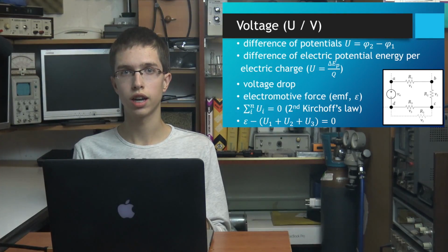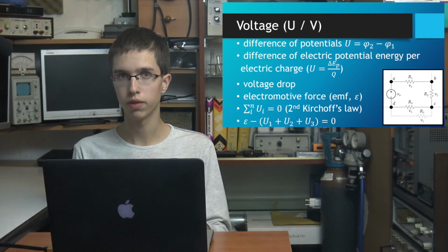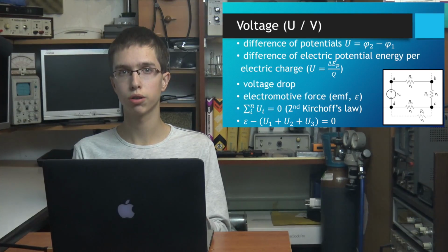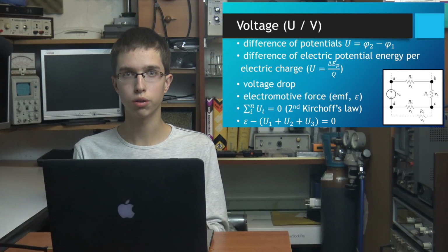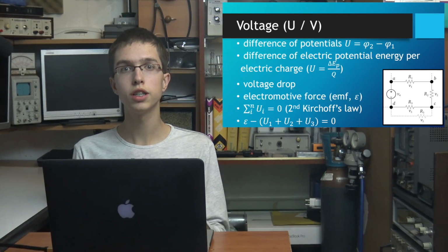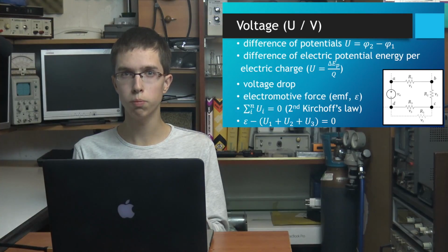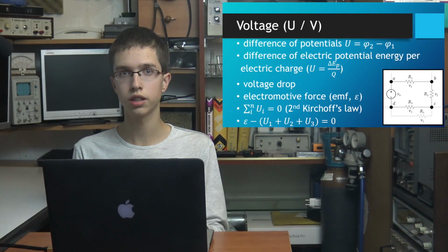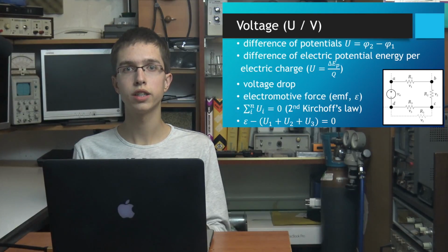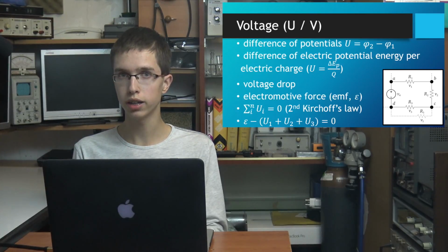Let's say it's the conventional current direction from positive to negative pole. Then imagine yourself going around the conductor wires of the electric circuit. Since you've begun at the positive pole, when we come to the next source, if there is one, we have to come firstly to its negative pole in order for it to be positive. For this you need to know that when two batteries have opposite poles connected, then it's said they're connected in series, meaning the total voltage in the electric circuit is their sum. If two batteries are connected plus to plus and minus to minus pole, then you have batteries in parallel.